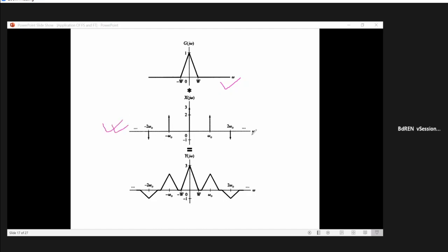It contains a series of impulses from minus k to plus k, because in both negative and positive frequencies the Fourier coefficients exist, and they appear as conjugate pairs. This side is for minus k, this side is for plus k. So the impulses appear at the locations of the harmonic frequencies.